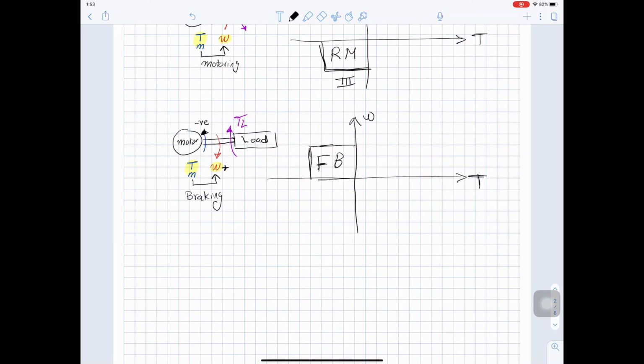To brake the motor or to stop the motor, you need to take the energy from the mechanical system. You can take the energy and lose it in friction, like when you use the brake in your car. Or you can have batteries in your car, and when you brake, you convert the car into a generator and take the inertia, or the kinetic energy, and convert it to electric energy and store it in the batteries, like hybrid cars. So braking doesn't mean you are regenerating energy. You will be regenerating energy if you have regenerative braking.